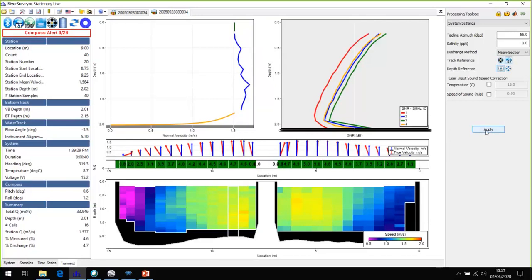And also with the profile being so flat, if you were to go there and do a current meter gauge at only 0.6 of the depth, they won't agree at all, because it's such a strange profile all the way across the river.